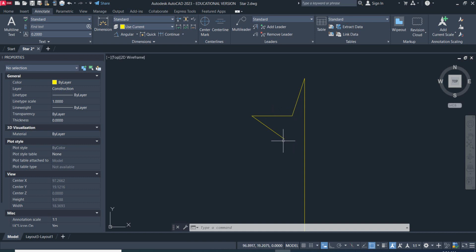And then I can go to my line command again from here. Same kind of thing as the very first one up there. I say at 2 units, tab, minus 108. And so that gets you part of the way around. As you're working the rest of the way around, the same thing is you're either adding or subtracting from 0 degrees, whatever it's going to be.